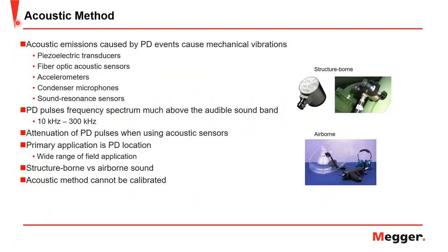Next, we have the acoustic measurement. The acoustic emissions are caused by the PD events that cause mechanical vibrations. And this can be picked up using piezoelectric transducers, fiber optic acoustic sensors, accelerometers, condenser microphones, or sound resonant sensors.